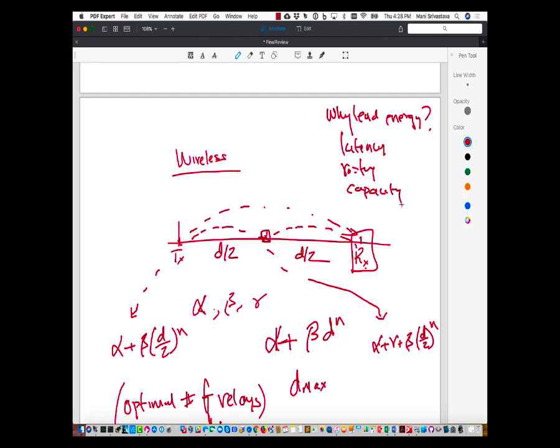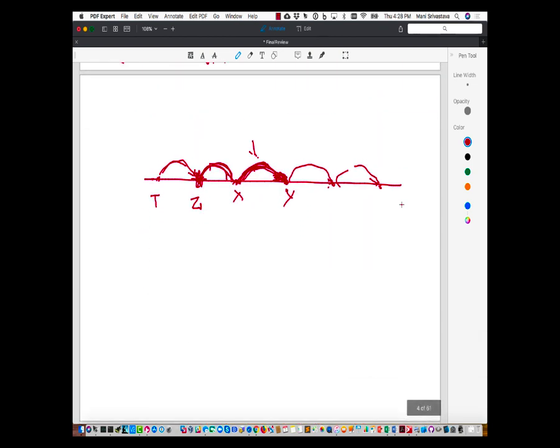I mean, yeah. So on this note though, wouldn't stuff like frequency domain multiplexing and all that help? Excellent. So I could separate them out, right? I could do something so that while X is transmitting to Y on one frequency, P can transmit to Z in a non-conflicting manner. Non-conflicting would mean either a different frequency or a different spectrum code, which serves a similar purpose. Okay, so absolutely. But you have to deconflict. If they're sitting on the same channel, so to say, then they're going to collide. Okay. So that creates kind of a challenge also.